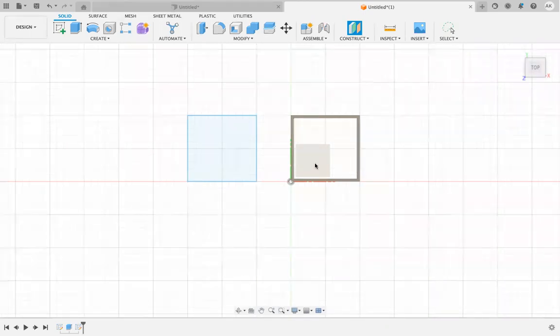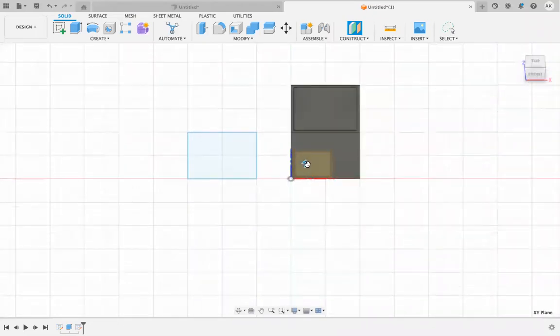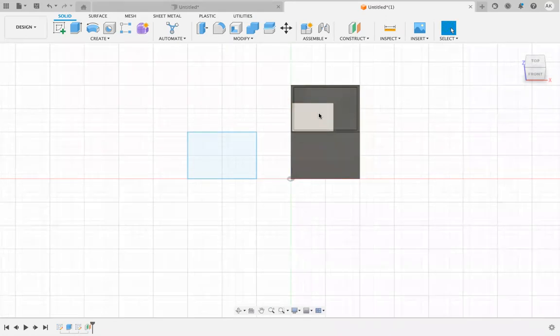The way you could do that is by using a function similar to offset. By going to this construction, you click Offset Plane. This does not have a key function. You select an existing plane. Then you go to your angled view and you could drag it up to however tall your house is. And then you set it there by hitting enter. Everything in this program is confirmed or set into your canvas by clicking enter.